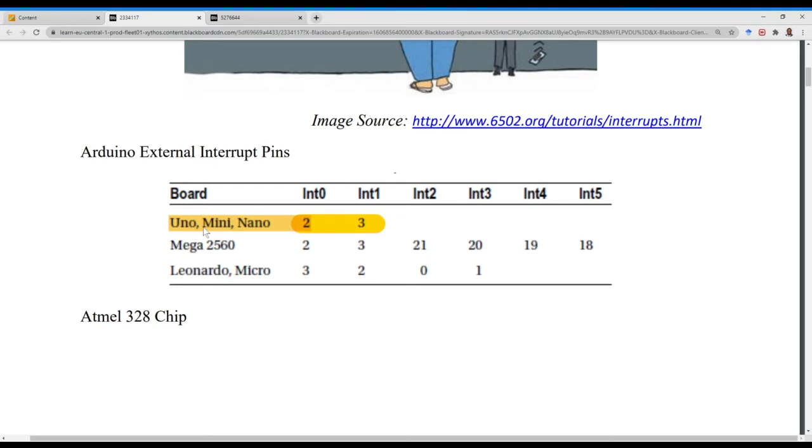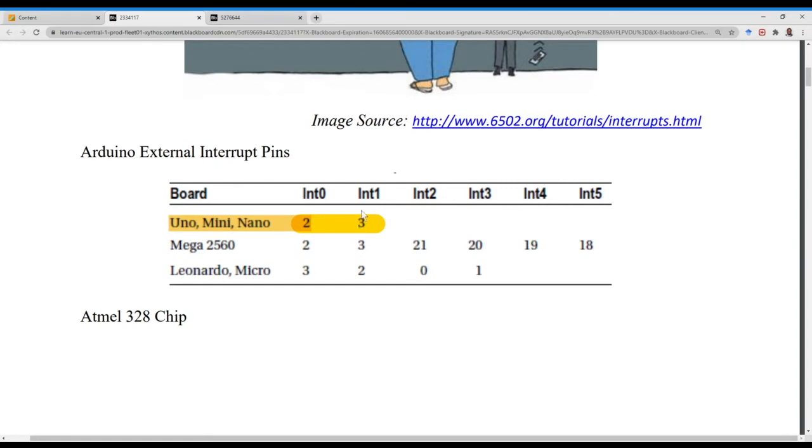On the Arduino Uno R3, you've got two pins that you can use as interrupts. So the other application that I said uses a lot of input pins, you can use 2 of them as interrupts. You've got pin 2 and then pin 3 that can act as interrupts.